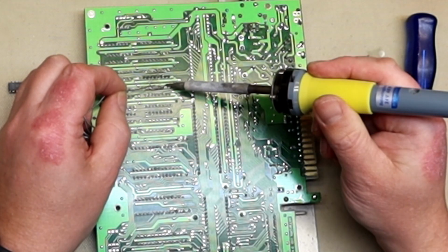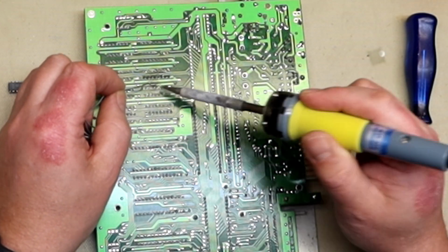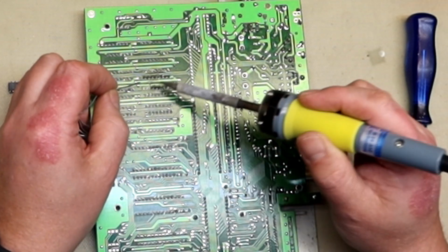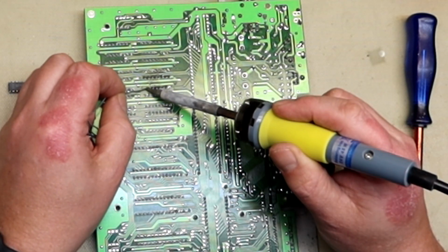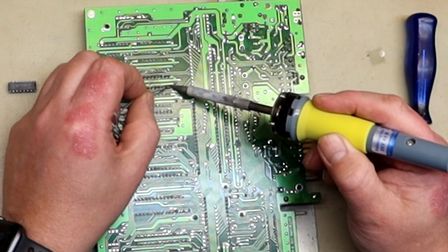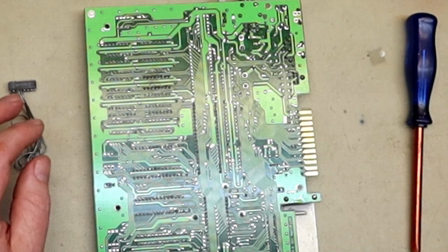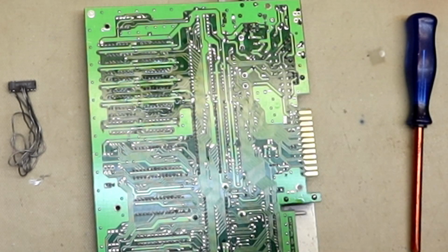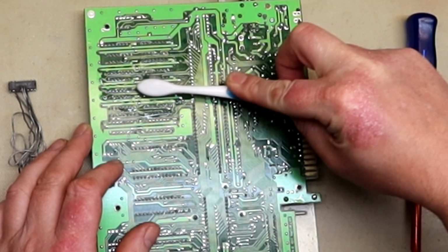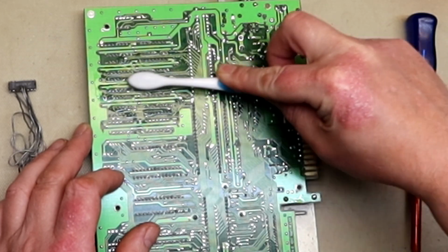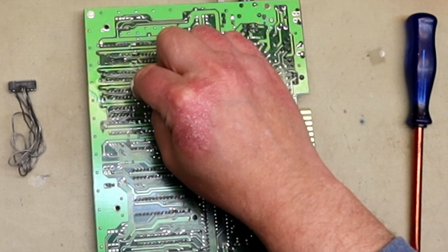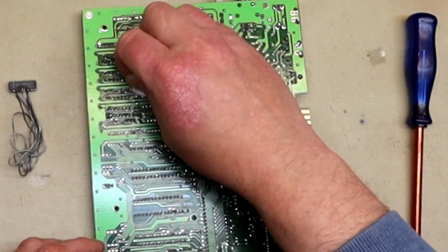And here I do kind of an experiment. I have used digital zoom in the editing software to zoom in on the soldering itself. So it's interesting to see how the quality of this looks when I'm finished rendering the video. And I'm washing all the soldering off with the isopropanol, as this is solder with a lot of rosin in it. It's very important to clean off the debris afterwards.